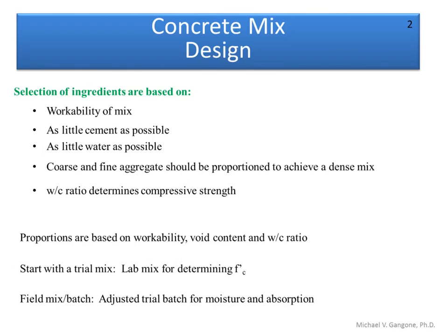We also want to think about the effect that water has on the strength of concrete, right? And we'll come down here just for a quick second when we talk about water-cement ratio. And we recall we drew this, or you should have seen this in the materials class, when you're looking at water-cement ratio versus the compressive strength of the concrete.